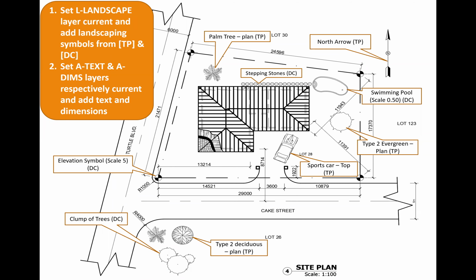So I'm going to move forward now by adding the dimensions and then the text. So let's go back to the drawing. Now, I am not going to put the dimensions in millimeter as I have it here. I'm going to put them in meters. So in order to do that, I need to create another dimension style, because the previous dimension style was created to put things in millimeters. So I want another dimension style that will give the measurements in meters and show the units. So I'm going to put the M after, so that nobody gets mixed up and think it's 29 millimeters and not 29 meters. So anything else that doesn't have the symbol will be for millimeter.